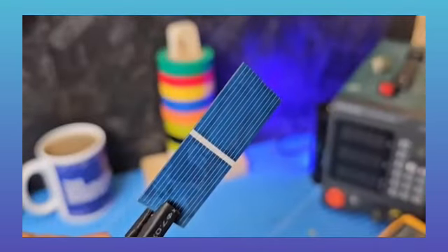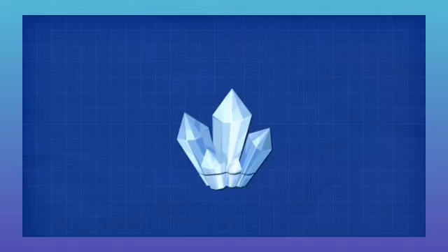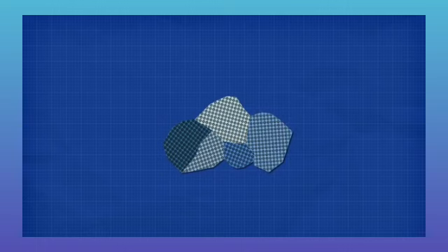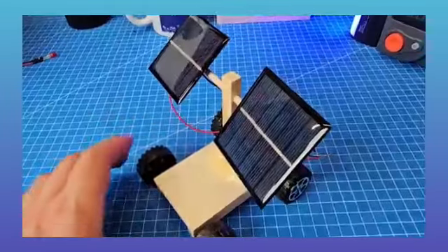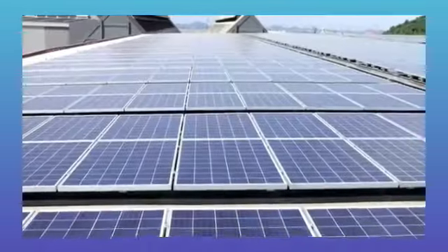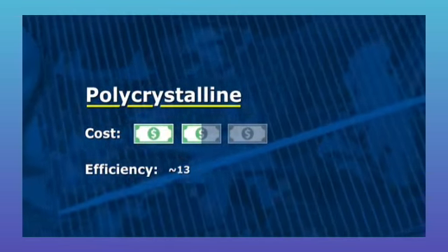One of the most common is the polycrystalline cell. It typically has these blue flakes, although we can get other colors like this emerald version. These flakes are individual silicon crystals, poly meaning many and crystalline meaning crystals. They look beautiful, but each crystal is a separate group of atoms in different orientations. The boundaries of the crystals are defects, and they actually reduce the efficiency of the cell. These are very common for hobby electronics, solar-powered products, and also in solar panels. They are relatively cheap, but have an efficiency of around 13 to 17%.